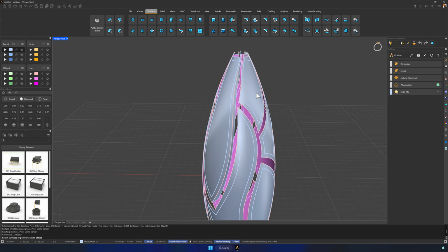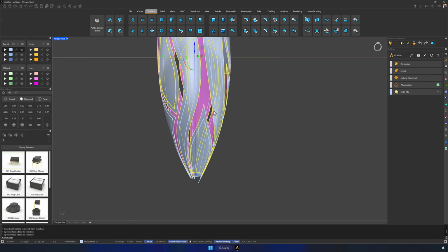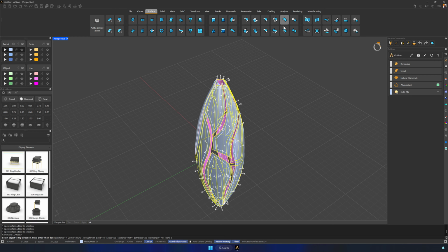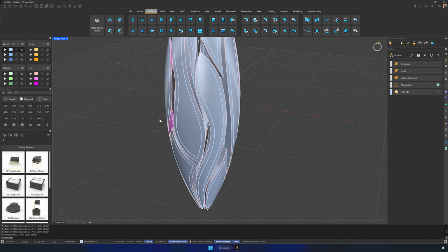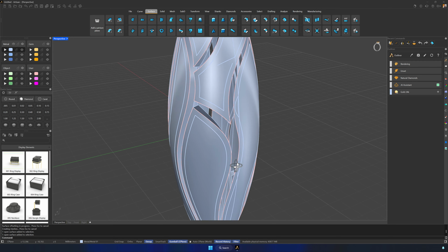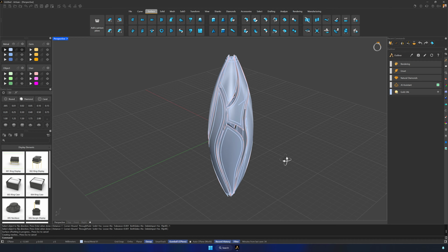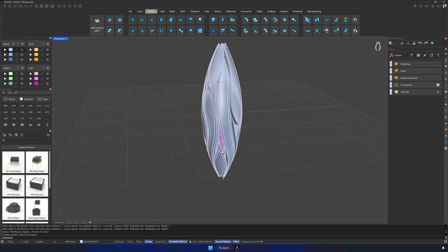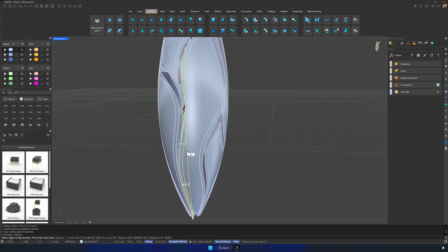We'll select them all and offset 1 millimeter. Click Flip All in the command bar so that they point toward the inside of the model. If we're missing any, we'll notice because we still see pink areas. In that case, we repeat the offset and confirm. We keep checking until every region has been offset correctly. Once we make sure that all faces have the desired offset, we can continue.